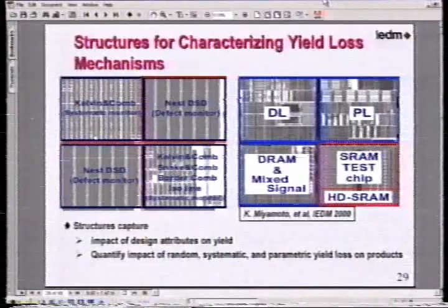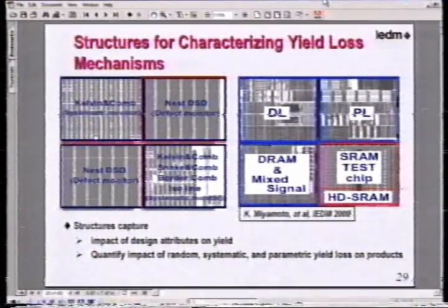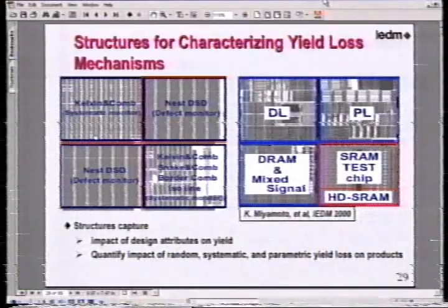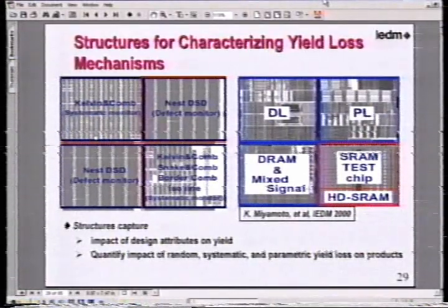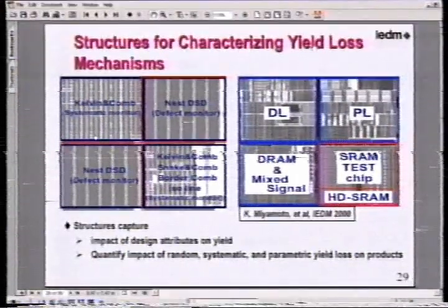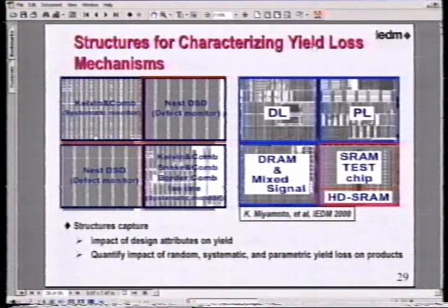We touched very briefly on the defect density and characterizing it correctly, and the electrical defect density. These are those structures. You also have structures which are Kelvin, snakes and combs, etc. You have conditions with bordered combs. All these are doing is telling you what kind of difference you will see under different neighborhoods or different attributes on your product. So this is the case where you'll be having vias with different chains, etc.